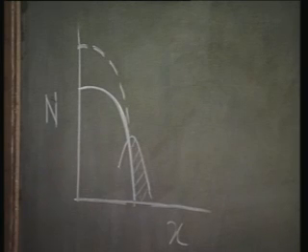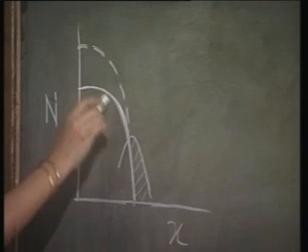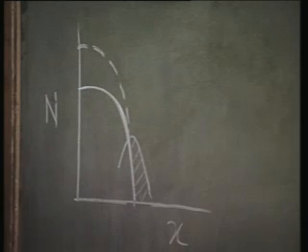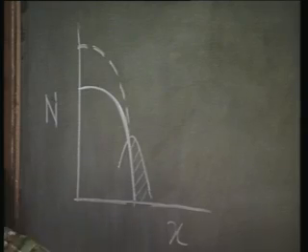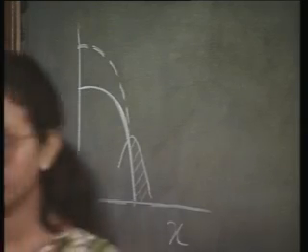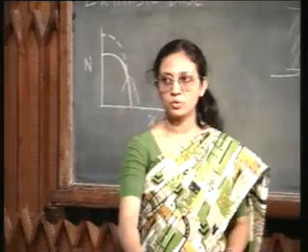Immediately below the emitter, whereas as far as the extrinsic base is concerned, you are getting the full benefit of the doping concentration. This of course will give you a better control over the base depth as well as over the base doping concentration.